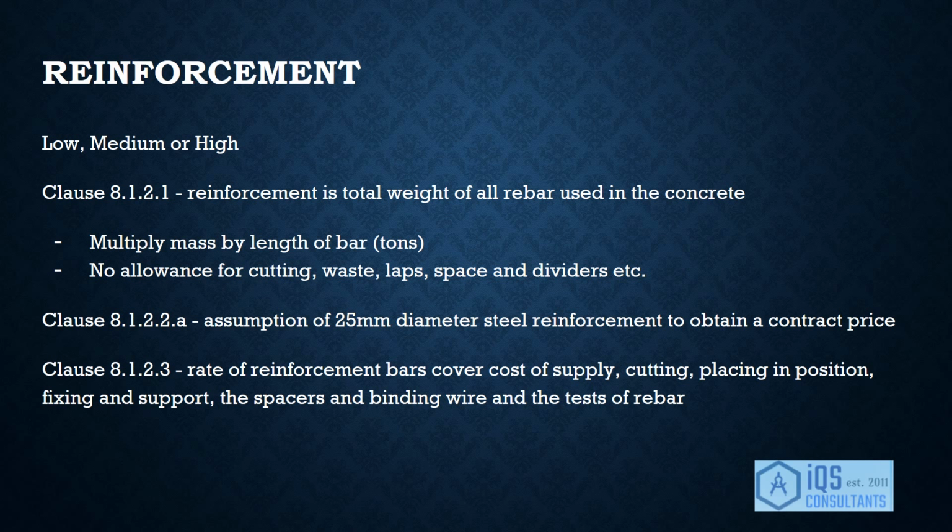The method in which to measure this is by multiplying the mass of the bar by the length of such bar. The unit in which the measurement is classified is tons. There should also be no allowance for cutting, waste, laps, space dividers, etc. An additional assumption should be made about the diameter of the rebar in clause 8.1.2.2a, which states the diameter of rebar is used to calculate the weight of reinforcement used in the structure in order to price it in tons.